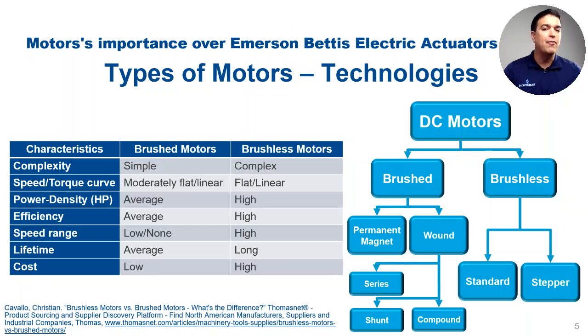Stepper motors have all the features of the standard ones, but you can control which pole the rotor jumps to, effectively allowing for precise stepwise rotational movement and high repeatability. Typically, stepper motors have 40 plus poles, and they usually don't have a rotational sensor, but they have simple drivers with some limitation on speed and torque. Printers are a good example of this kind of motor.